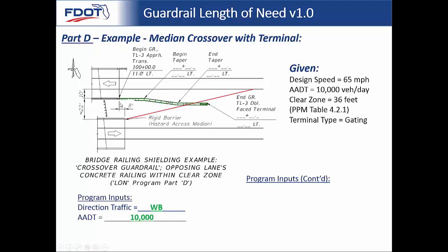So typically, the first thing that you start with is that edge of the rigid barrier. And you wouldn't be worried about having a nice even round number as a station. We just happen to give that to you. And so this does seem a little strange because we're kind of working backwards. We gave you this nice even round number for a guardrail station. And so now we're going to have to spoil that nice even round number a little bit and work backwards to give you the face or the edge of the rigid barrier.